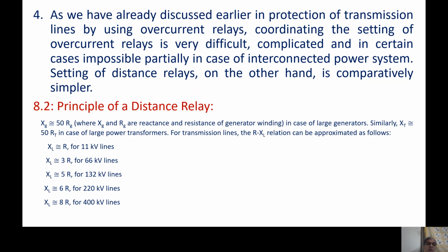The principle of distance relay. What is the principle of distance relay? That is what we would like to see. To start with, I'll say that for a very large generator, 210 megawatt, 500 megawatt, Xg, that is the inductive reactance, is also in 3 parts: the subtransient reactance, transient reactance, and steady state reactance.